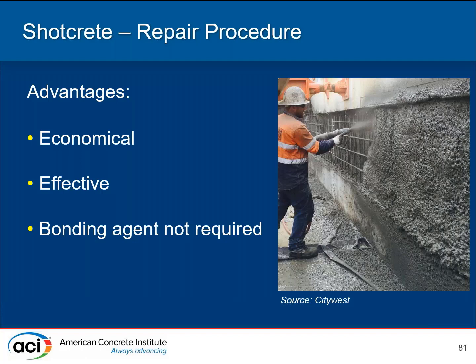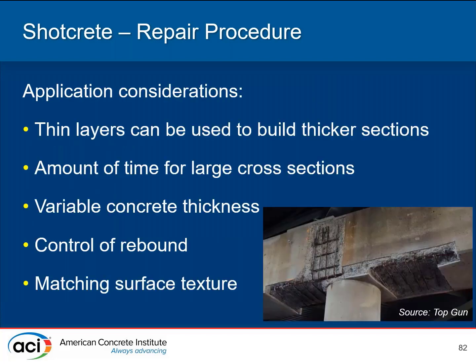There are some advantages. It can be very economical. You don't need to build a whole bunch of formwork. Because you're forcing things into it, you don't need a bonding agent, and you end up with the concrete where you need it to go. Disadvantages: you do need to deal with the rebound, and you need to make sure you're not getting any voids, you're not missing any areas. It really depends upon having an experienced operator at the end of the nozzle, the one who's applying it, making sure you end up with a good situation.